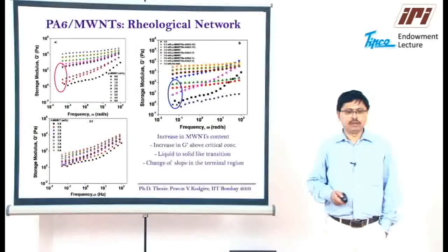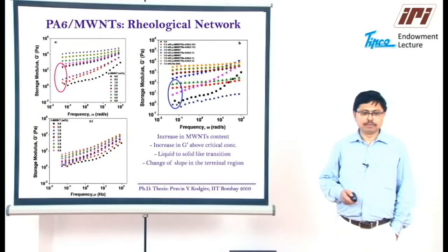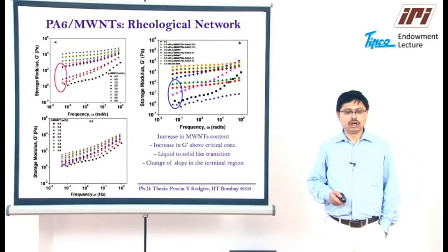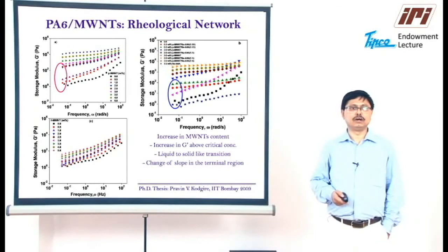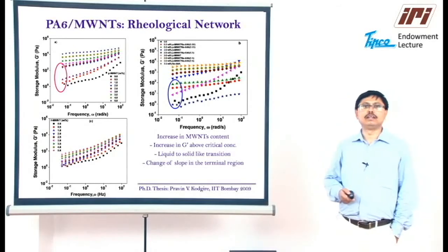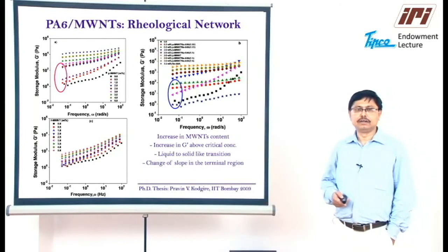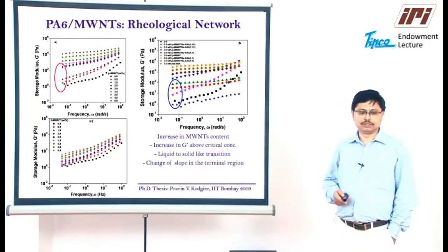The rheological network-like structure formation in these composites was also characterized through dynamic oscillatory measurements in melt rheological experiments, for the purified multi-wall nanotube composites, the functionalized multi-wall carbon nanotube based composites, and the composites incorporating NaHA modified multi-wall carbon nanotubes.